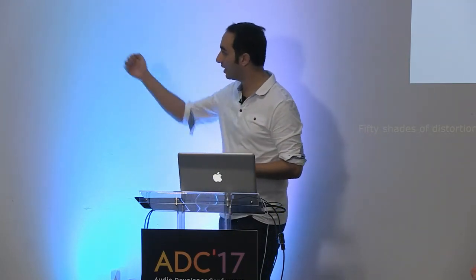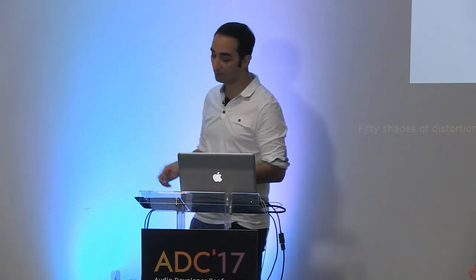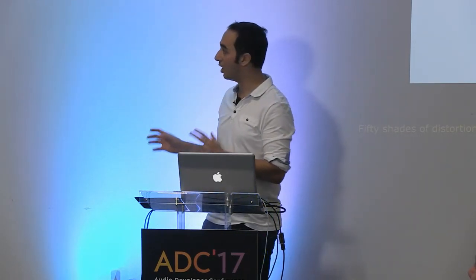Because of this feedback loop, if we try to write what is the output depending on the input, we will get some elements related with the output everywhere in the equation inside nonlinear functions, and we won't be able to write an explicit value for our output. So we will need to use Newton-Raphson to be able to compute the result in real time in a given distortion algorithm.